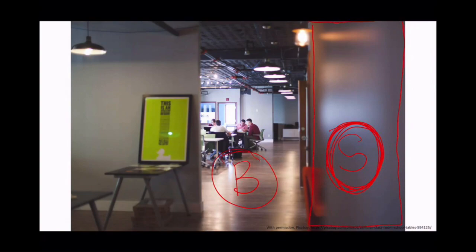Likewise, if the code says each floor can be up to 20,000 square feet with B, but only 10,000 square feet if the building was S, you have to limit the whole building to 10,000 square feet, because it's not fair to not separate the two and then get to choose the one that's more lenient. So that is the non-separated path.